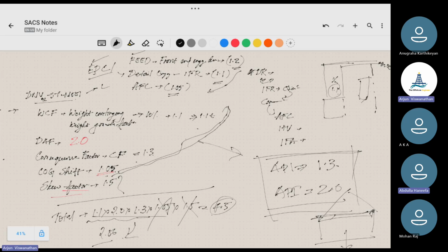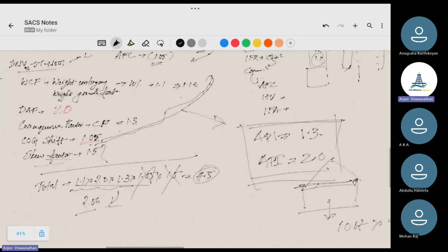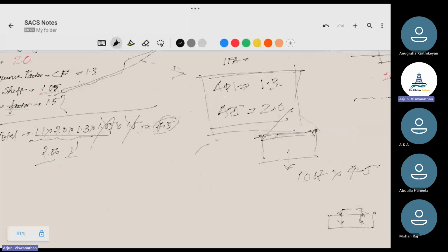API is very, I would say, less conservative when coming to the lifting. And for other checks, API is very good, like pipe check and all. But for the lifting, API doesn't consider much about it. But when we come to DNV, because API most of the time deals with bigger structures, that's why their factors are all less. Because whenever we have a bigger structure, when the weight increases, the dynamic amplification also reduces.